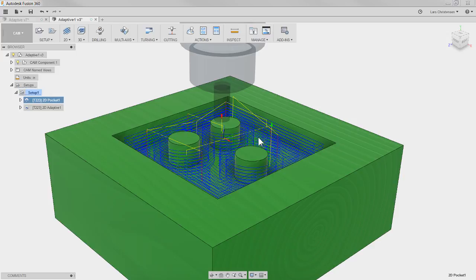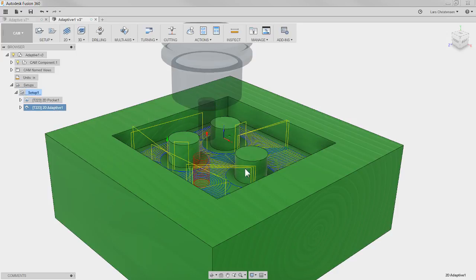When that broke down, you put more load on the cutter from a spindle standpoint. You had a lot of Z moves every time you went 100 thousandths down, putting pressure on the Z axis and the X and the Y, whereas side milling with an end mill is the gentlest way you can do it. That means we're putting less stress on the cutter, but also on the machine. So adaptive clearing by itself is not a kick-your-butt toolpath that you need a crazy machine for. It literally just side mills out.